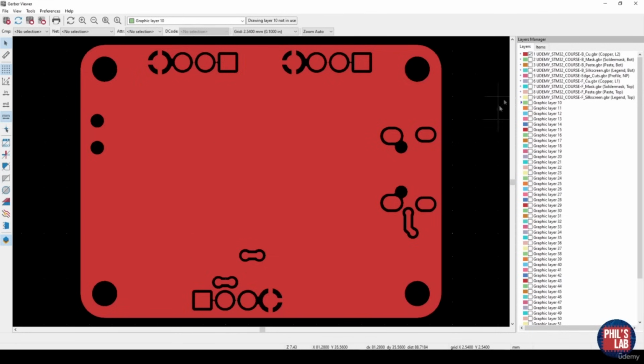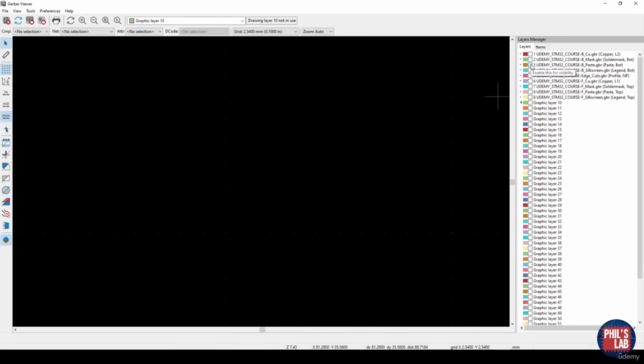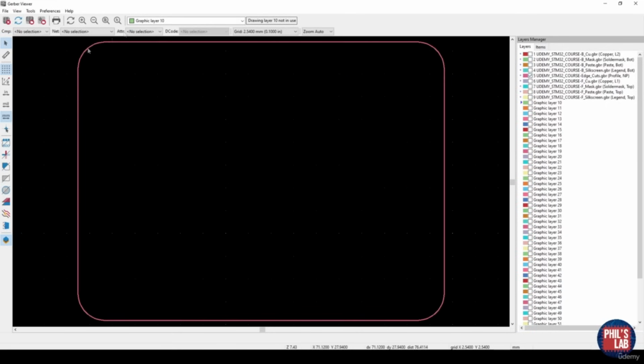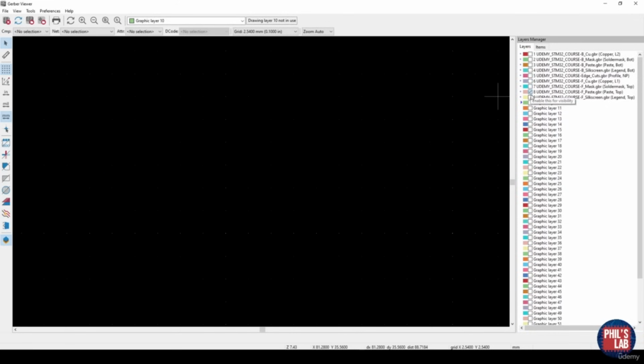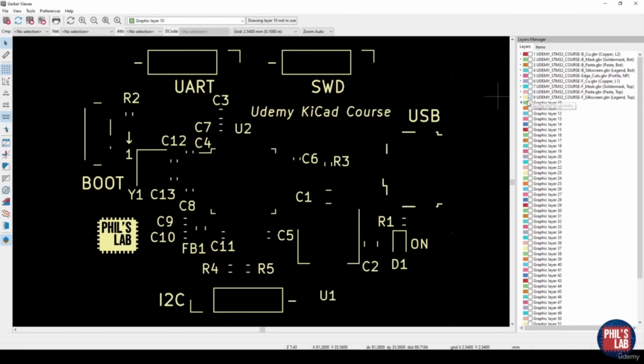So this looks okay. The mask layer, paste, silkscreen is the bottom text, so to speak. The edge cuts, which is our outline. Front copper, which is our kind of most interesting layer with the MCU, and this is how the copper will actually be deposited, or rather etched away from the board. Front mask, paste, and silkscreen. So it pays off to take some time to really check your Gerber files, check for any shorts, or anything that doesn't look right. Oftentimes you will discover some mistakes in those.